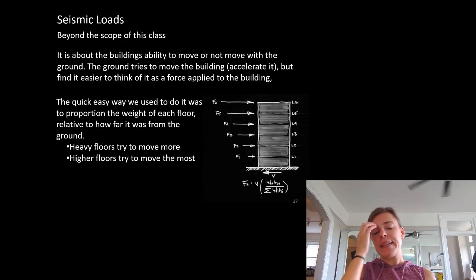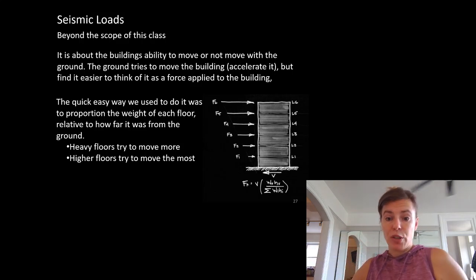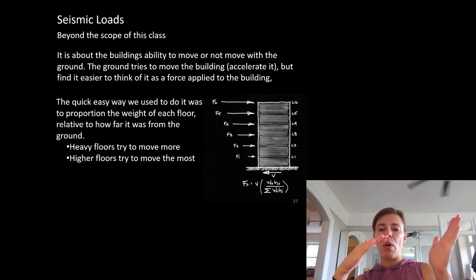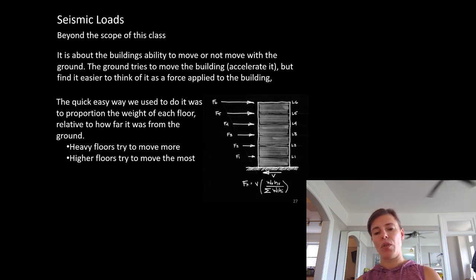I've said that structural design hasn't really advanced much or had much development in 100 to 150 years. One of the places that is not true is in seismic loads. Seismic loads have seen real advancements in the past 50 years, mostly due to our analysis software. We have been able to make our design much more complex to make our buildings more resilient and less expensive. Resilience, or you can use resilience in a few different ways. Maybe make our buildings more ductile. Ductility is all about movement and how much we let our building move. Movement also absorbs energy or takes a certain amount of energy.